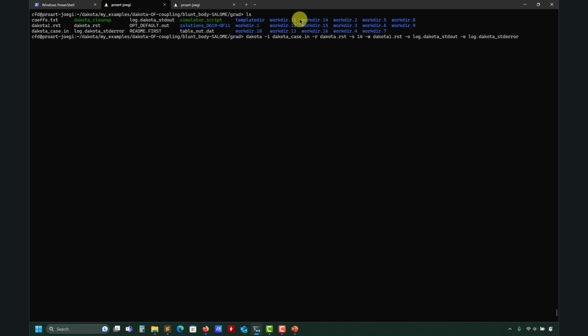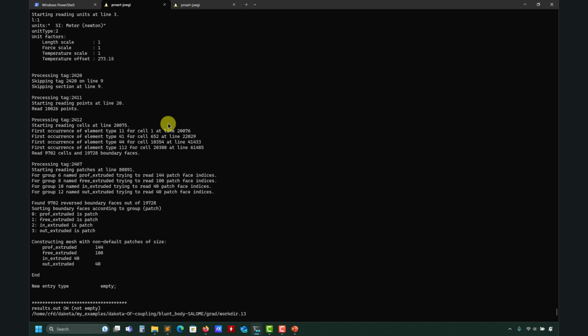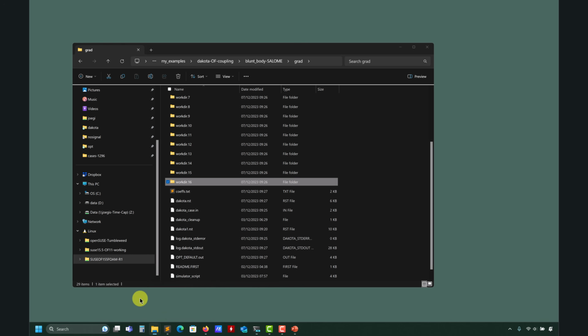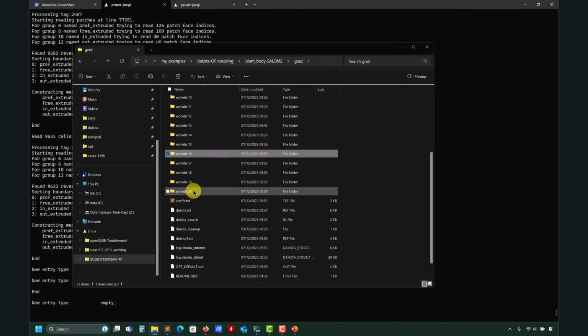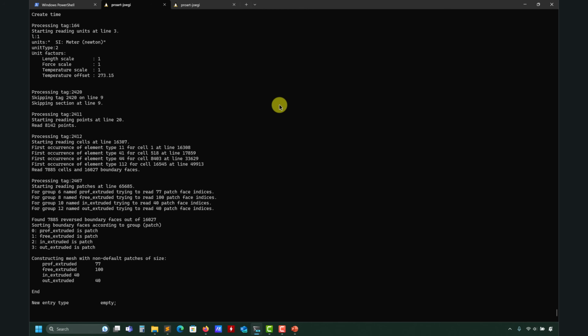I want to start from this function evaluation and then save with a new name and then save the standard log file. So let me go here and launch this and see that it is starting from that case and it's launching everything. So as you check here, you will see that you have all the function evaluations. You are not starting from scratch. So this is the restart capabilities and the failure capturing.